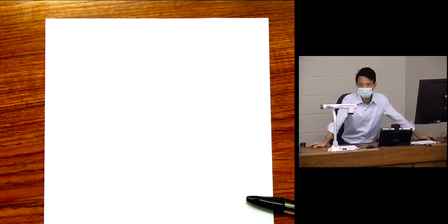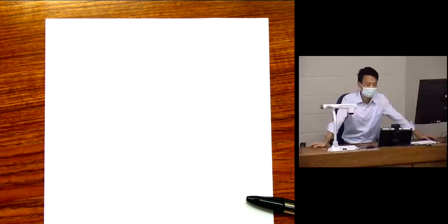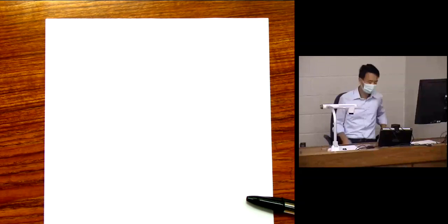So remember the energy release rate and the fracture energy: the unit is energy per unit area, so it's joules per meter square, for example. And when we say rate, it's not a rate with respect to time. It's with respect to an advancement of crack area. So it's still a rate, but not with respect to time. So when you say energy release rate, just be careful what comes to your mind.